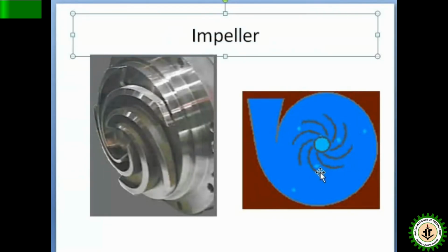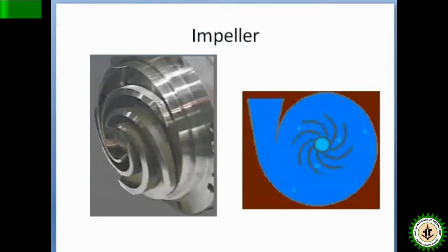Reverse vane angle is used to improve the pressure and the kinetic energy. But if you use a forward vane angle, it will not improve the pressure; it will increase the degree of homogeneity in the mixture. So whether this impeller is part of agitation or part of pumping, you can understand by checking the vane direction, whether it is rotating in the forward vane or the backward vane. That is the basic principle you have to remember for centrifugal machines.